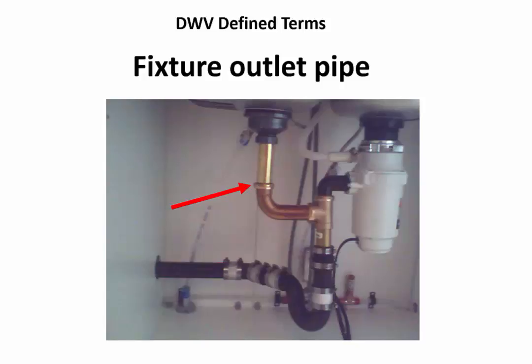All the piping upstream of the trap is considered outlet piping. Continuous waste configurations under a 2-compartment sink is another example. Most fixtures are limited to a maximum allowable outlet pipe length of 1200 millimeters, as stated in Article 2482.